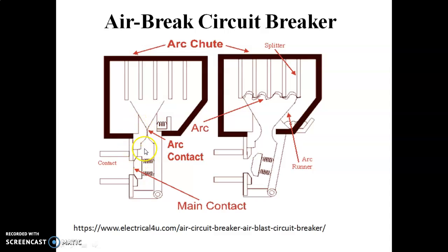Okay, see, when the breaker is in closed position, position means what? There is no fault condition, it should be a normal condition. At the normal condition of the system, normal supplying voltage and current, at that condition circuit breaker is in the closed position, right? So when circuit breaker is in closed position, the main contact carries the what? Current. Okay, but it should have the low contact resistance. Okay, see, when it is in the closed position, main contact is closed and arcing contacts are also closed. When the fault occurs, it should be opened.